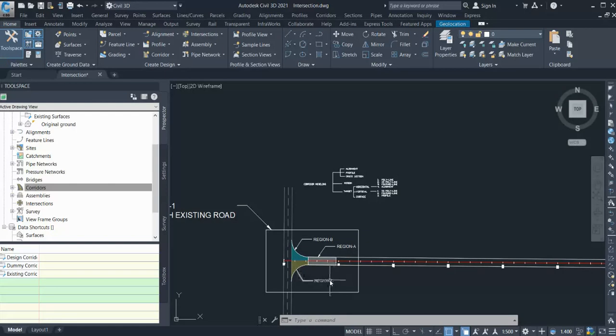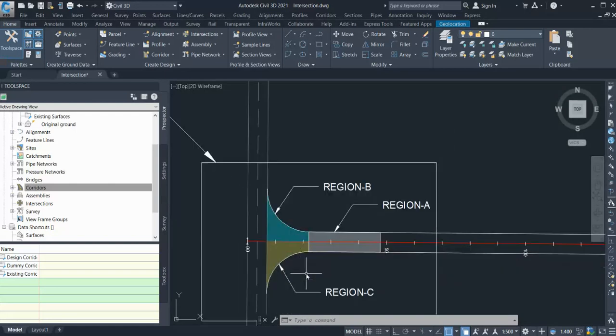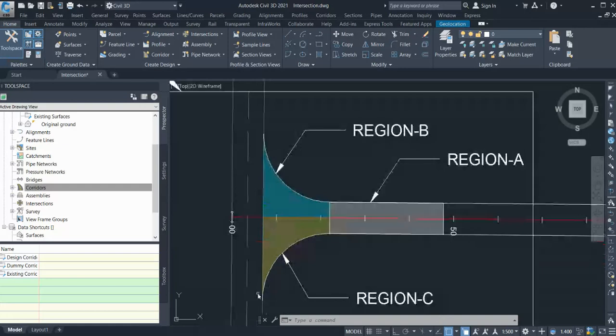Second, you need to decide your regions, and then you have a target. Well, not everything can be built with the normal assembly, like in the case of this curve return assembly. Here you can see I have a varying width. If I have to model this, I cannot model it with the 3.6 normal assembly or normal cross section. This is varying width, so in this scenario I need targets. In this area, I have to have a horizontal target so it can connect to these edges, and also a vertical target because I have to connect with the level. So it will be a smooth connection.